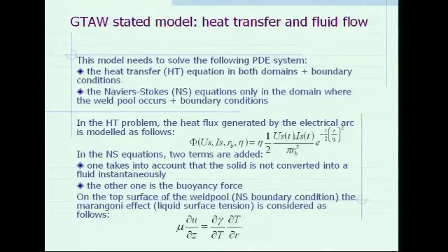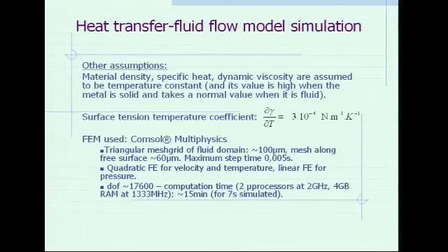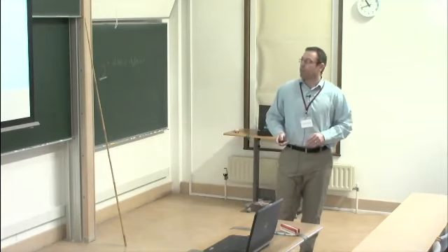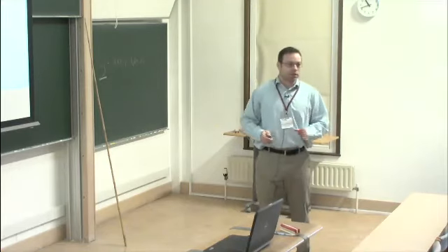In this study, I will take it, as I said, to a constant value, but I didn't say something as well: this one depends on the temperature, but also on the composition of the steel, and mainly on the sulfur content. So if you don't know the sulfur content of the material, you are not able to simulate it. So it is not a question here, because this one can be characterized experimentally.